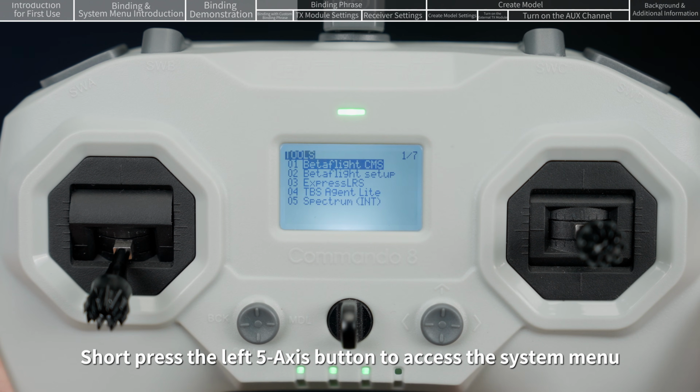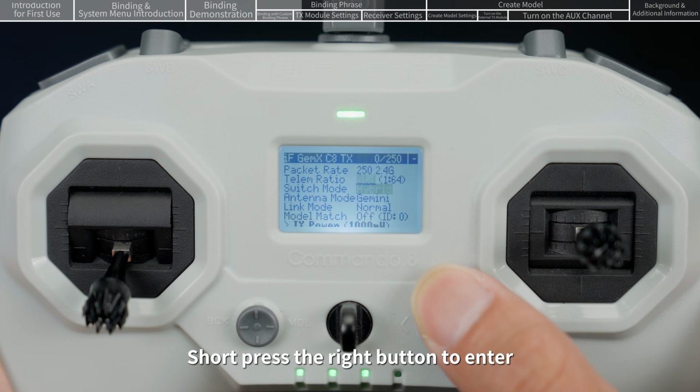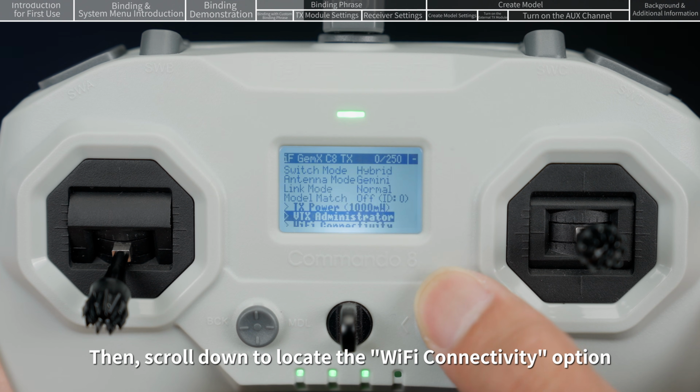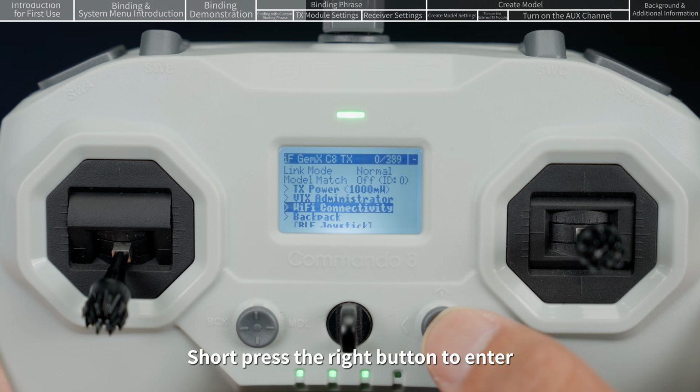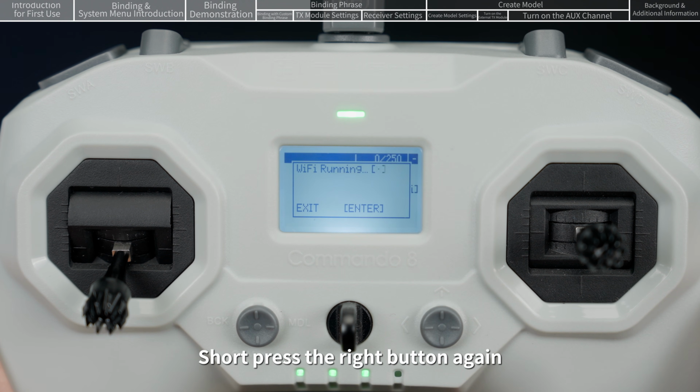Short press the left 5-axis button to access the system menu. Select the Express ELRS option. Short press the right button to enter. Then, scroll down to locate the Wi-Fi connectivity option. Short press the right button to enter. Select the Enable Wi-Fi option. Short press the right button again. The TX module is now in Wi-Fi mode.